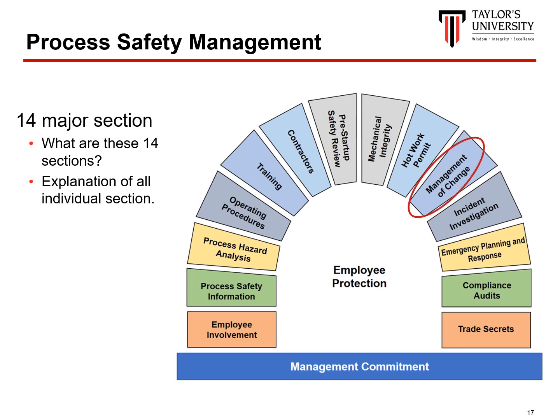Under the management of change section of the PSM standard, employers are required to develop and implement documented procedures to manage changes in the process chemistry, equipment, and operating procedures. Before a change occurs, it must be reviewed to ascertain that it will not affect the safety of the operations. After the change has been made, all the affected employees have to be retrained and the pre-startup review is required to be conducted.